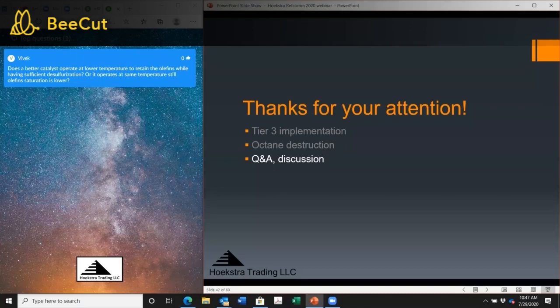process. Of course, as you push more sulfur down out of the light naphtha and get it into the sulfurizer, you get the sulfur out, but you're also pushing more olefins down there. And they're usually the olefins that are in high concentration, and so you lose a lot of octane. So there's a good optimization that you can see and do with the model for the cut point on the light and heavy naphtha if you have a splitter, and the end point. I think those are